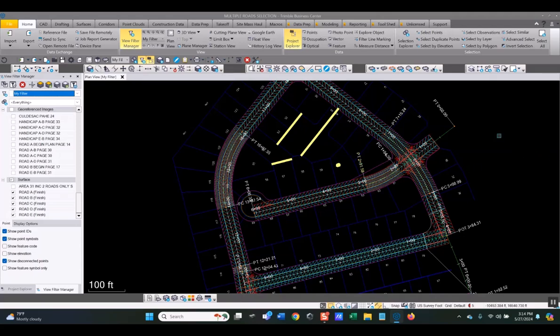Okay, great. Well, the reason I wanted to back up from select by layer, that's the one that I start with, is select by layer. When I'm wanting to move something, I'm wanting to copy, I'm wanting to change its elevation. Well, it's normally on a particular layer of data. All right. So in the light of picking onesie twosie entities, pick one, hold down the control, and pick.